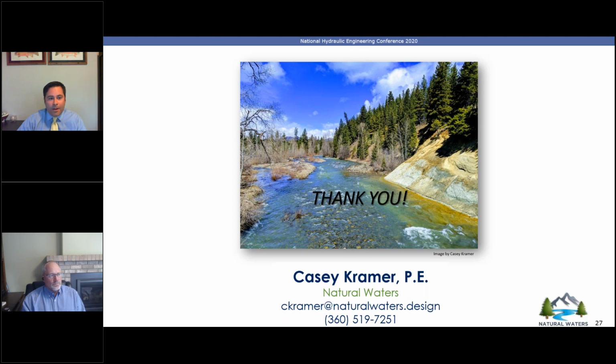So yeah, you're right on, Wes. As Scott alluded to, that coordination with your survey crew is essential. I highly recommend that hydraulic engineers go out with the survey crew at the scoping level to get an idea and set the domain and the limits that they need to get the right hydraulic model completed.